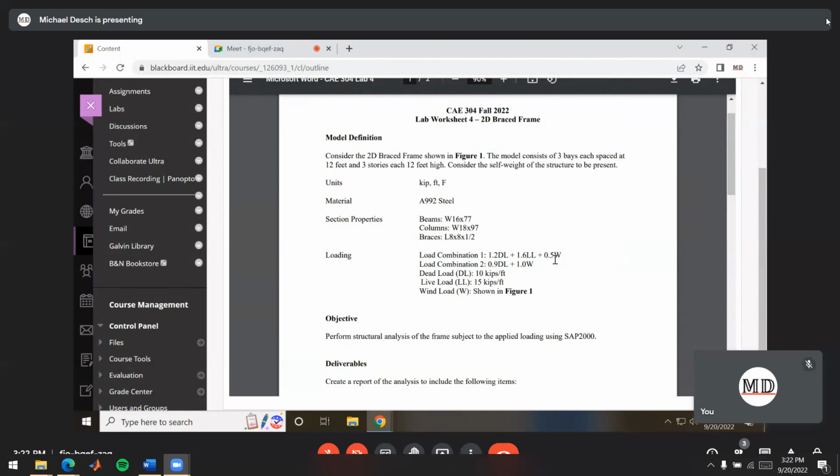If you've got a library, they move those books around sometimes, so those can be considered live loads. If it's a storage place, all the weight of the items they're storing in there could be live loads. So stuff that can enter and leave the building, basically.